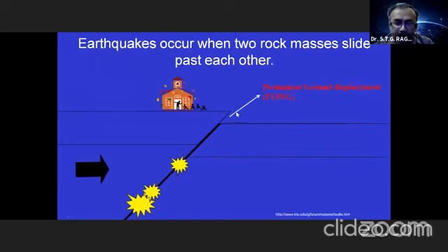And here is one more important thing you can see. This red one shows that after the end of an earthquake, the rocks behave like plastic. They can't go back to their original position. You will see a permanent offset here, which is known as the permanent ground residual displacement, or in seismological terms, the fling. This is a very dangerous thing in the near-field region. Just imagine this house was located here; nobody can design one column this side and one column that side. So it's very difficult to design structures located on top of the faults themselves.